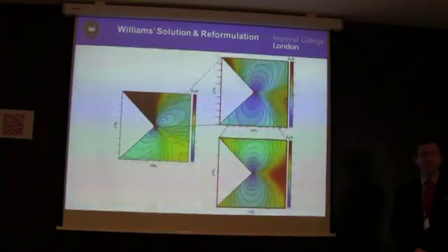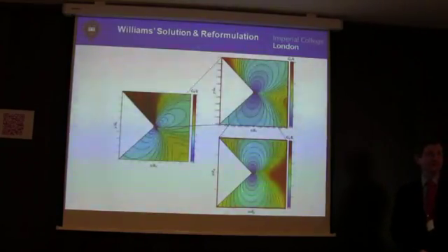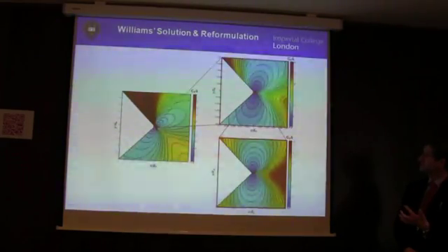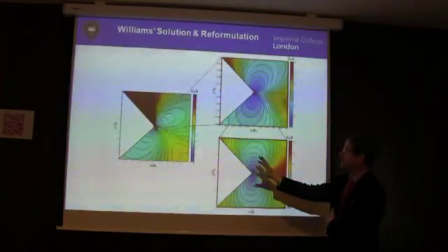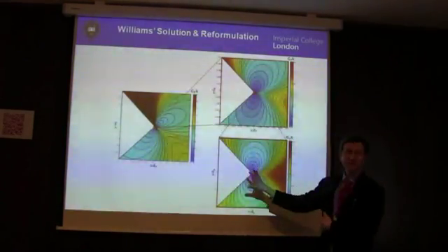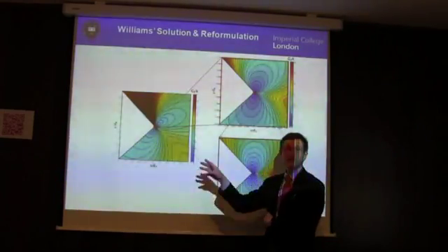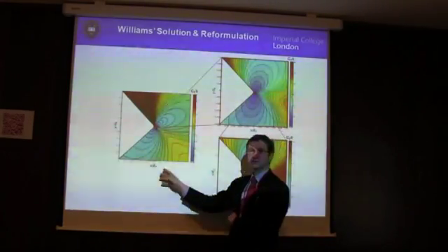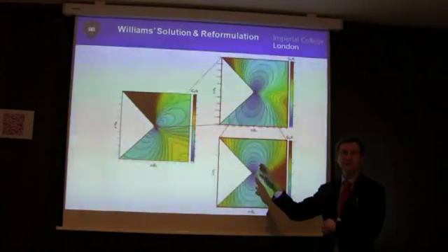and it made me think about whether or not it was possible to do a justification. Right, now what I've got here are a set of plots of simply von Mises yield contours. I expect you're very familiar with these. Let me just explain a little bit more about this. So there are three plots here on different scales, and these are obviously physical dimensions, but they're for the semi-infinite problem, so that the x and y are normalized with respect to that thing d naught, which I'm at the moment carrying as a parameter.